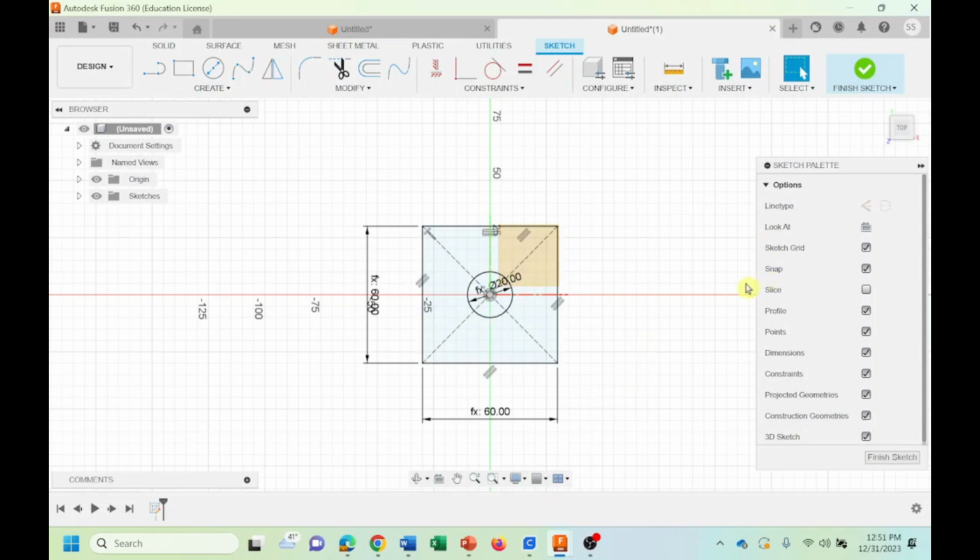Now I want to have another one, so I'm going to use a construction line. I put the line from here. I'm here, push tab. So 0 degrees, another tab. Here I push O, which is the offset. Click on that. I already defined the offset, right? And enter. So I have that line, which is here.